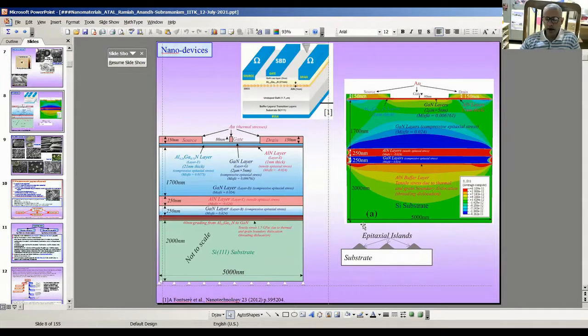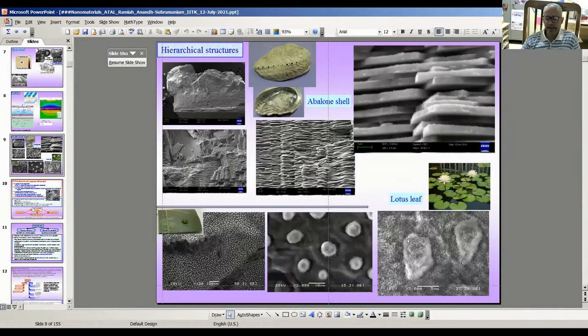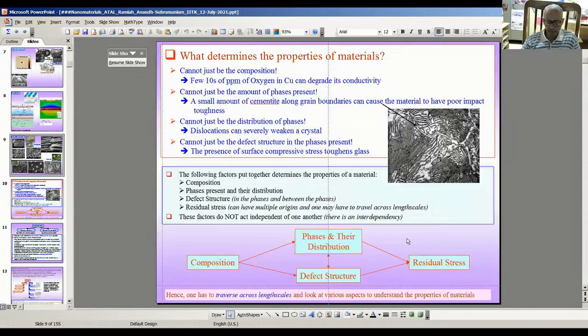You put a capping layer and then grow a second layer, then you will find there is a strain alignment. That is, the second layer of those epitaxial islands may be growing exactly over the first layer, though they may not directly see them.